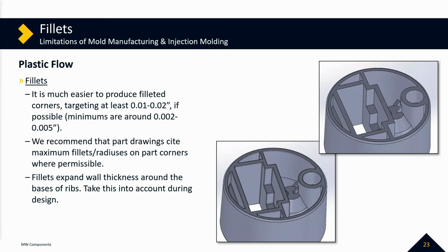There are also areas like along a parting line where the steel is meeting steel that can't be filleted or shouldn't be filleted. And so that's something that we'll go over. We often go with the customer and talk through that. And that's something that should definitely be considered as you are moving through the design phase and looking for a DFM analysis and that kind of thing.